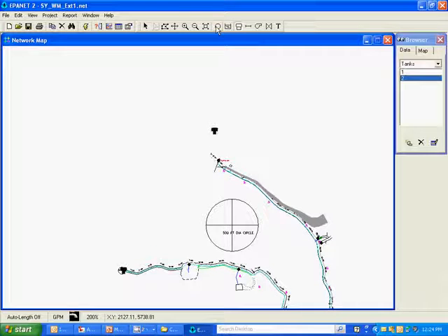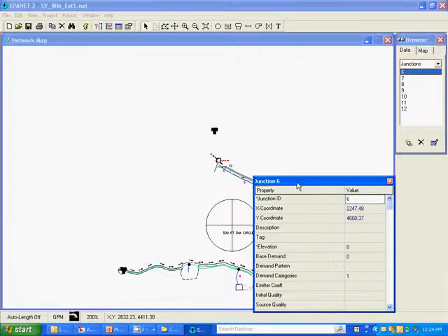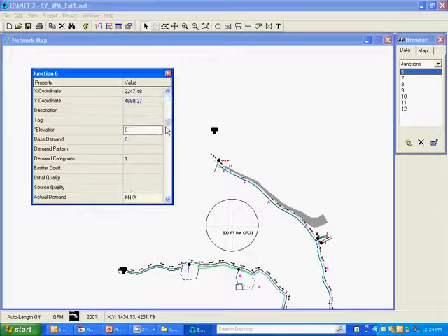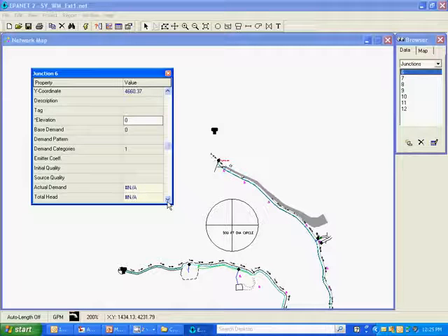Now I'm going to go ahead and start to edit the nodes with known survey data, values for parameters of each of the nodes. This is the beginning of the system. You can see here it set its elevation as default as 0. We want to change that to 3596. The rest of this can stay the same. There's nothing else there we need to change.